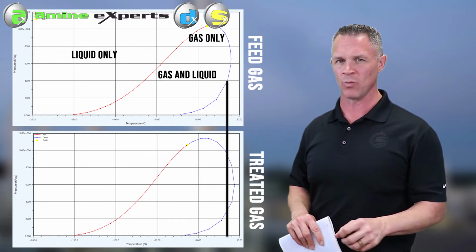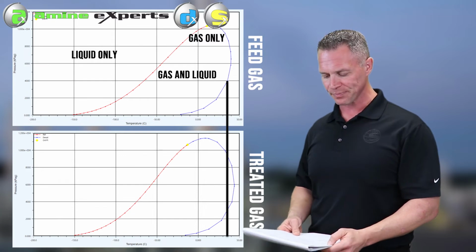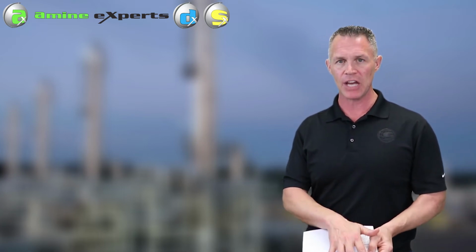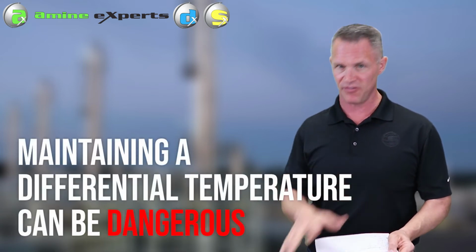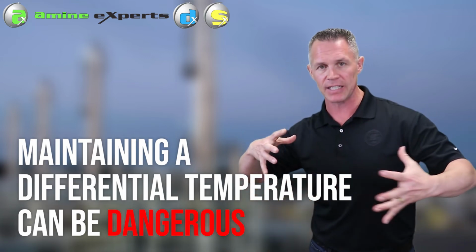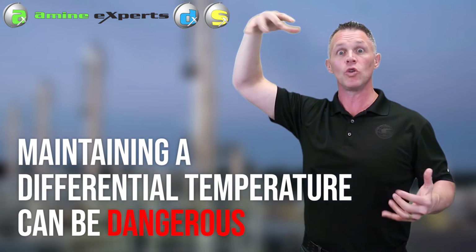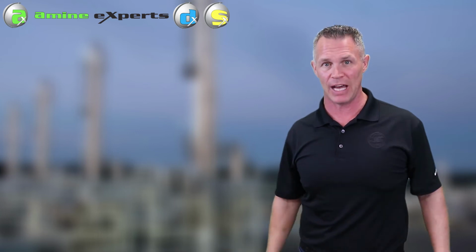Again, a simulator can help you fine tune what the differential temperature should be, if one's even required at all. Now, finally, our question came to us from a gas plant. In a gas plant, they're going to have a really strict H2S level allowable in their treated gas. So one of the dangers of blindly following this rule of thumb of keep the amine warmer than the gas is, if the feed gas temperature rises and the operator reacts by increasing his lean amine temperature to maintain that differential, you can put yourself off spec on H2S, which defeats the whole purpose of having an amine plant in the first place.